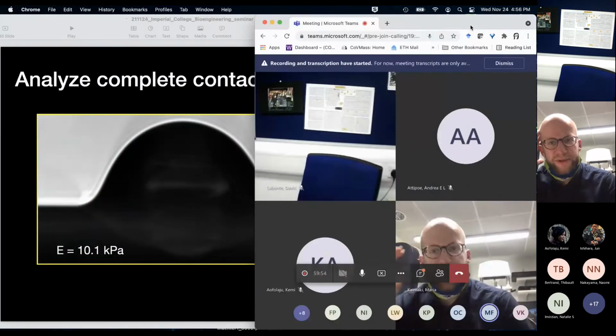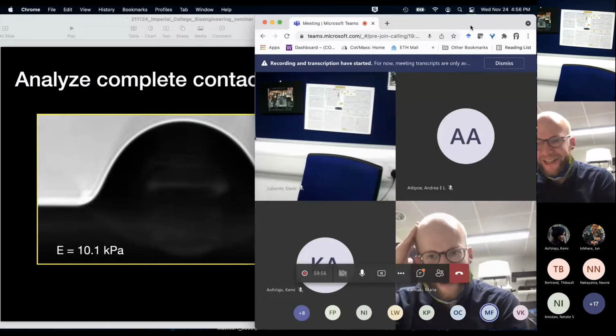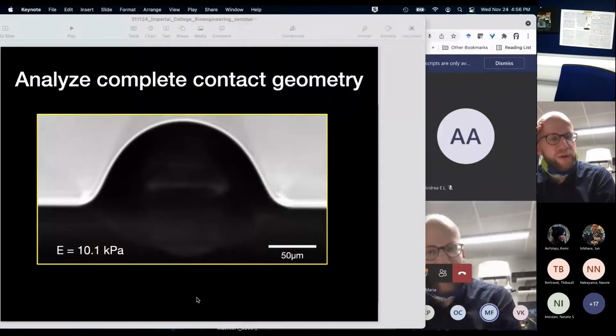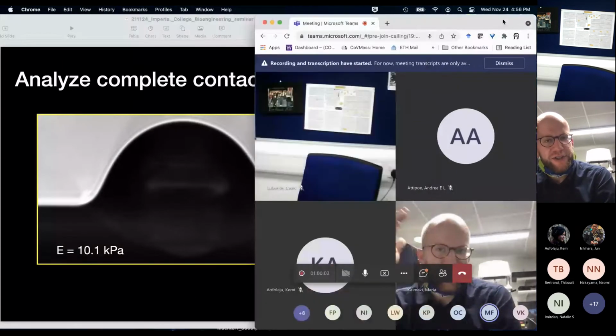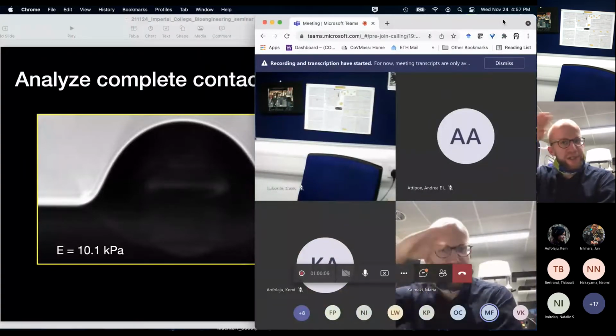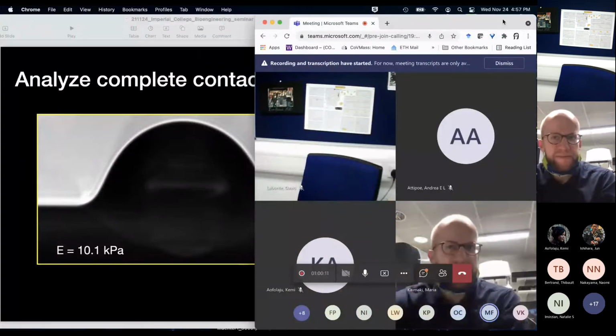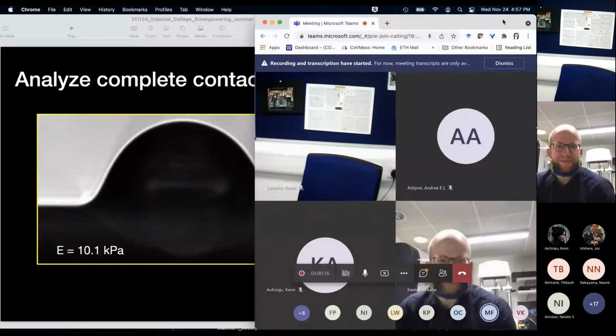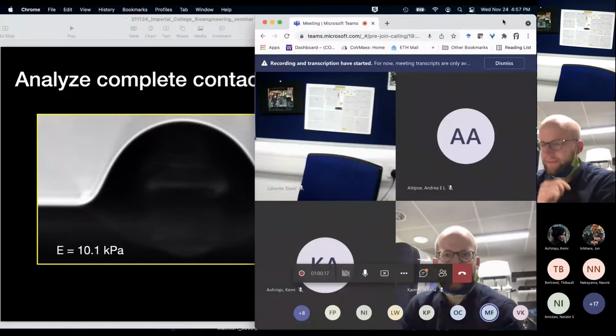Yeah, thanks a lot. Keep the questions coming. I have a question for you, Kate. Yeah, please. You mentioned this 18-degree limit, and you said basically we're looking at a wetting limit. So that would suggest that independent of the softness of the sphere, if you start to manipulate the surface energy of your glass substrate, you should be able to cut off the evolution of that curve early. Yes, and you can, and we have. We haven't totally finished analyzing those yet.